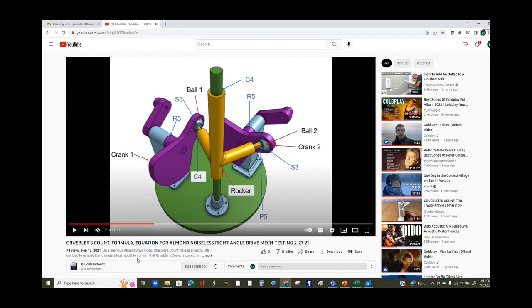Another thing I'd like to share with you is, do you see this little mechanism right here? Does anyone know what it is? It's an oil pump rig. Right. And as I'm running here, you can see this is like a ballast weight, and this is what it does all day, right? But they're not using the right joints, because if you don't mount these perfectly in line, they have revolute joints everywhere, and it can bind.